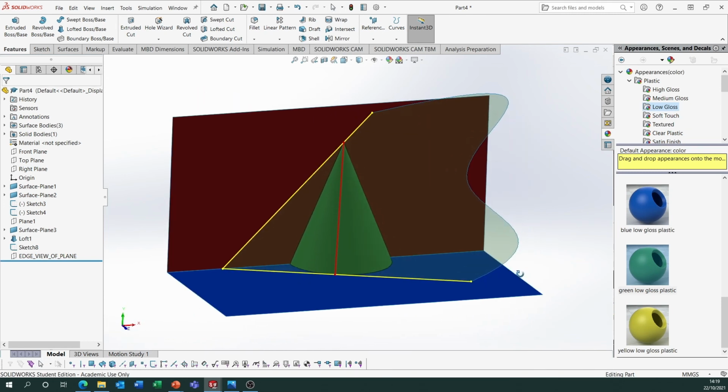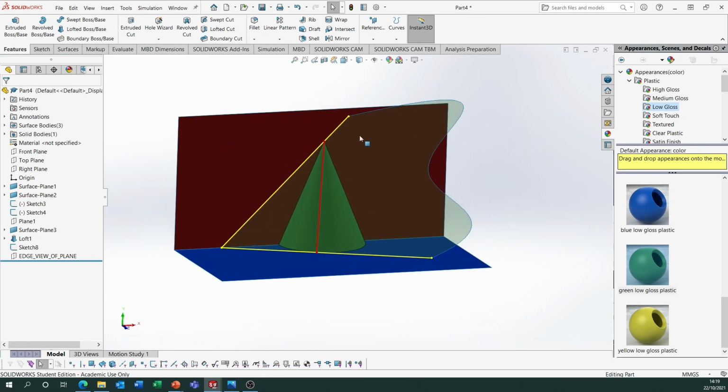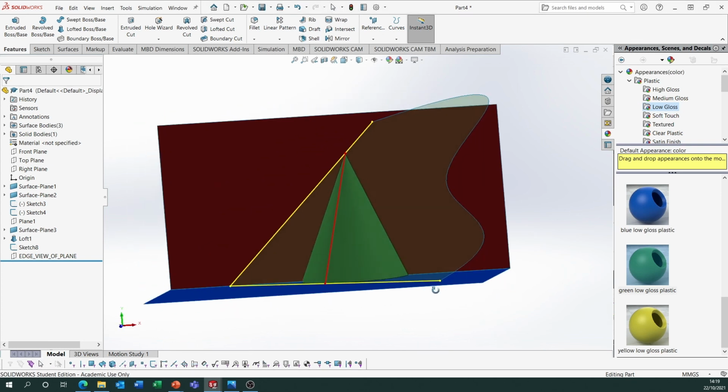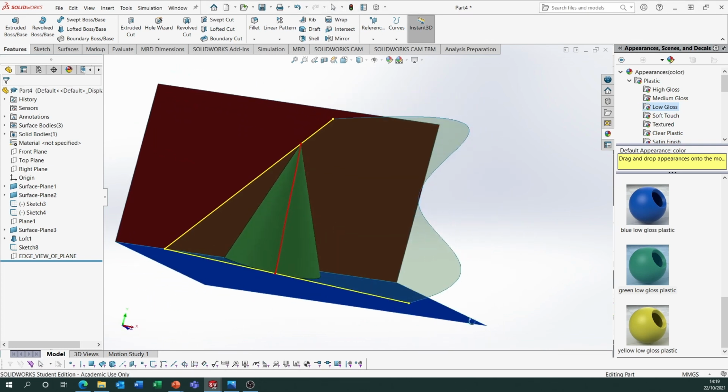Okay, so when you've got that done, present that on a drawing sheet as normal. Put your three drawn views in, your plan, elevation, end view. Make sure to label them and put in a pictorial view as well. So decide yourself whether you want that to be isometric, dimetric, trimetric, or just a random angle. You can label the model, or if you want, you can label it in the drawing sheet as well. I'll leave that up to yourselves. But once you've got that done, just make sure to put it on the sheet normally and export it as a PDF.